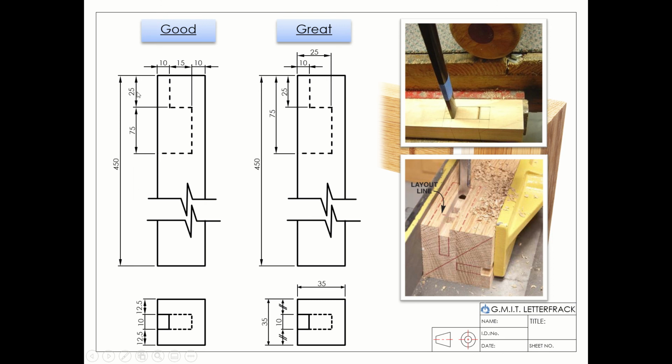Now we've got our chain dimensioning here for our mortise. Here we have our datum dimensioning. In this case, which is better? You could actually argue for both here. Each one is perfectly good. It's nice to be able to use a reference point like that, but if this distance got larger than, say, a typical ruler, well, you'd prefer to use your chain dimensioning to mark the piece.